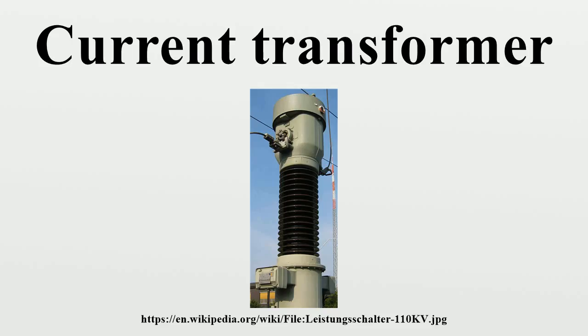A high-voltage current transformer may contain several cores, each with a secondary winding, for different purposes. A neutral current transformer is used as earth fault protection to measure any fault current flowing through the neutral line from the Y-neutral point of a transformer.